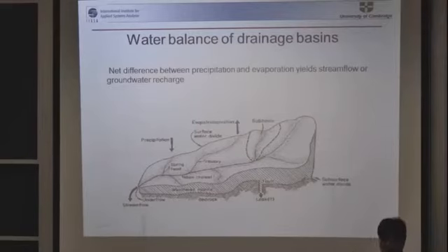There is also stream flow, which we can measure, and which is a product of this precipitation. There is groundwater percolation. On one hand there is precipitation, and on the other hand there are flows and groundwater flows or percolation, and there are losses. So in sum, there are three things, and the fourth thing is changes in soil moisture.